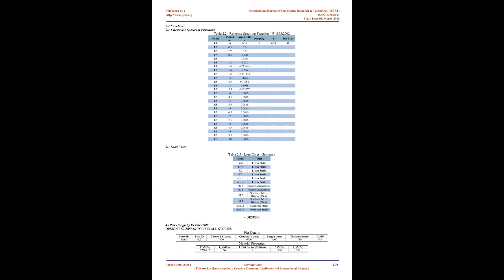It has been concluded that L-shape, C-shape structures with shear walls are having great outcomes in base shear, story drift and displacement. In all shapes, the I-shape building with shear wall is having increased base shear both in X and Y direction, and the L-shape is having very less increased base shear. The building with shear wall gives better execution against the seismic tremor when compared with bare frame building.